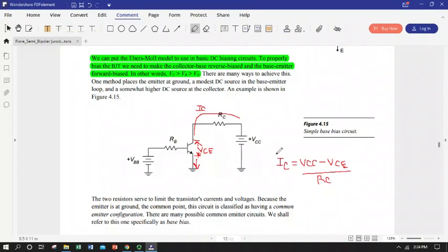Okay. So if I rearrange terms from a Kirchhoff's voltage law expression of voltage going on this path, and then rearrange my math, I could get this expression for collector current. Okay, this is part of the external circuit, VCC, and so is this. And here's my mysterious collector emitter voltage. And this is a line equation.